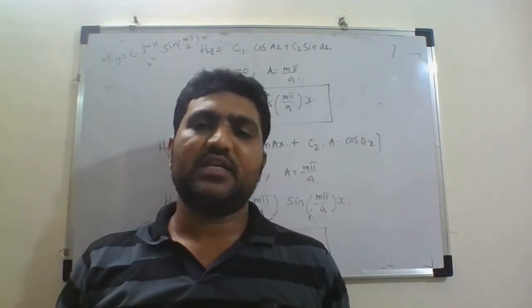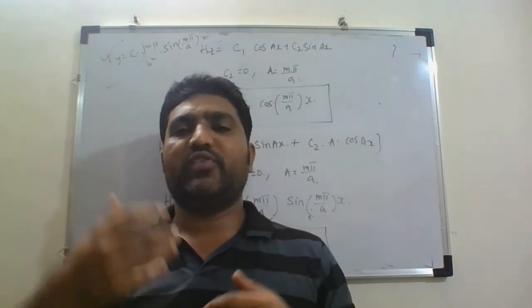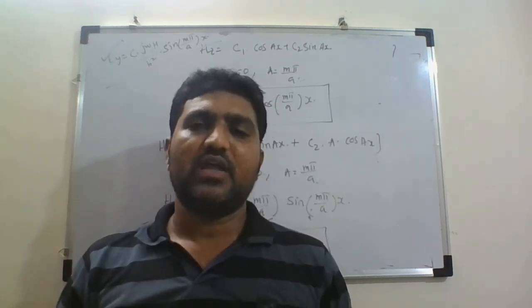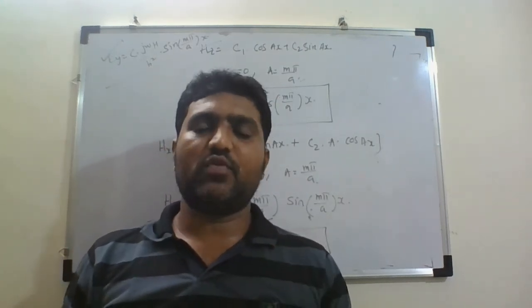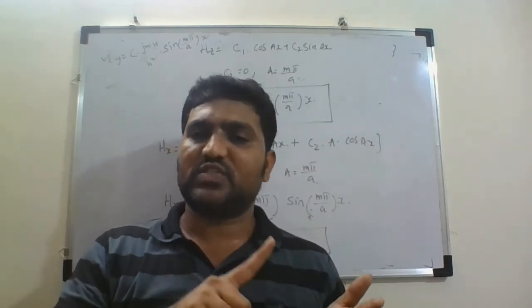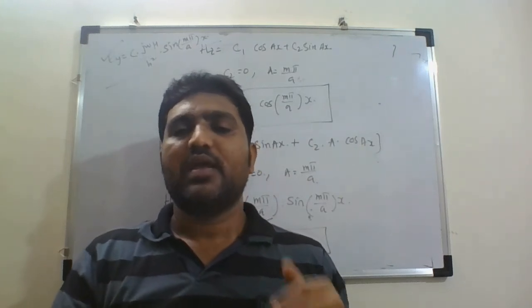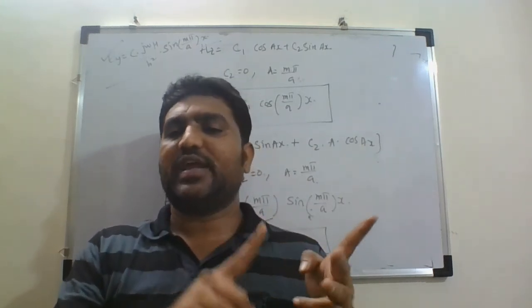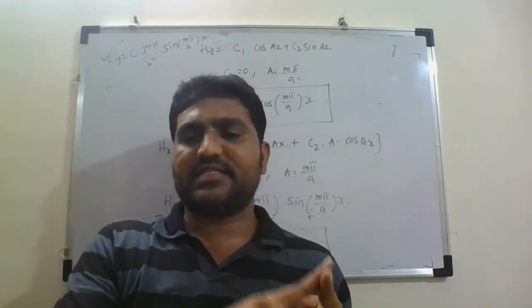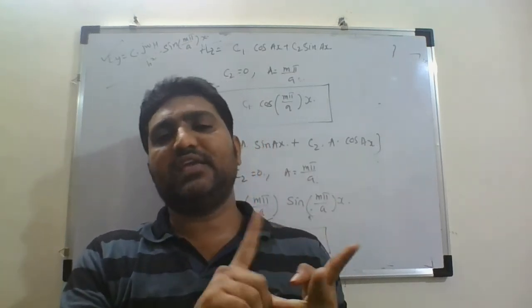Using this and the general analysis, we have found all the expressions for the remaining field components. We have observed that Ez is equal to 0, Hz exists, Hx exists, Hy will be 0. In the magnetic field, Hx and Hz will exist, Hy will be 0. For the electric field, Ex and Ez will be 0, only Ey exists.